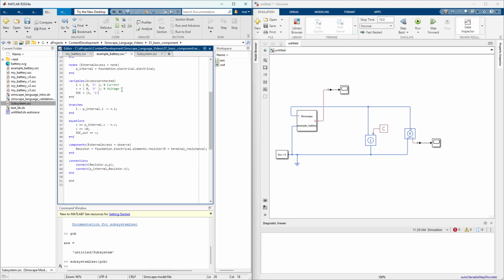It represents an amount of energy stored, but it's a value between 0 and 1, regardless of how much energy is stored. And so normally we might do energy stored here, but it's actually going to be easier, since everything's based off of SOC, if we use this SOC.